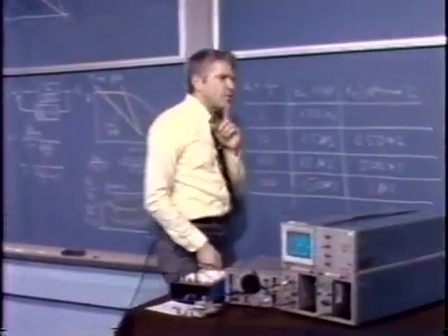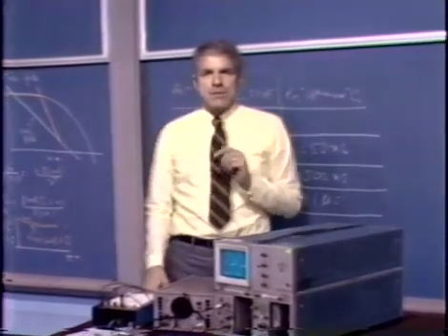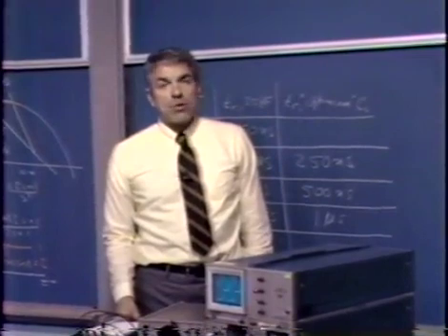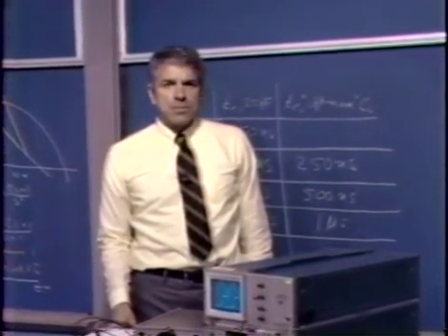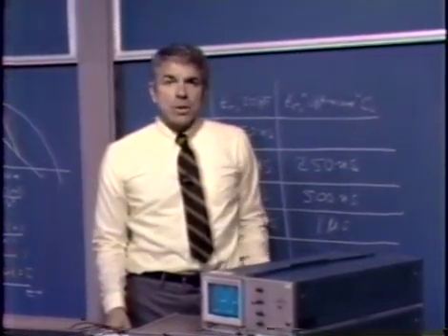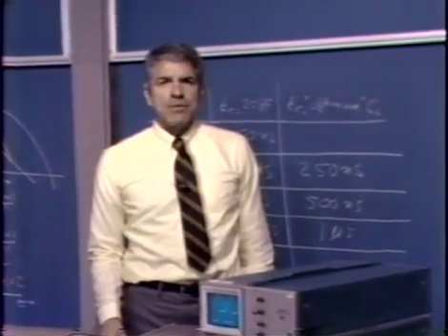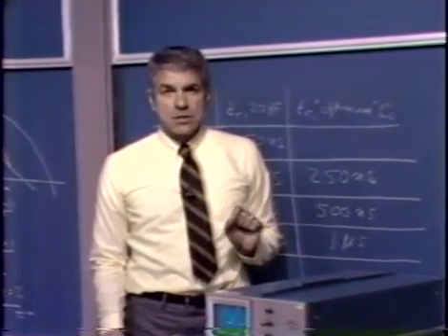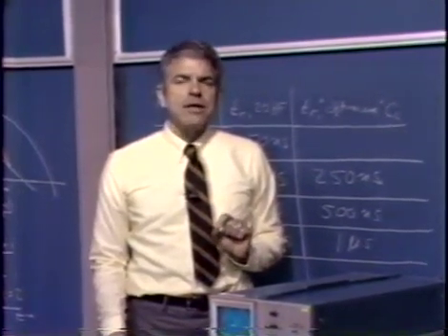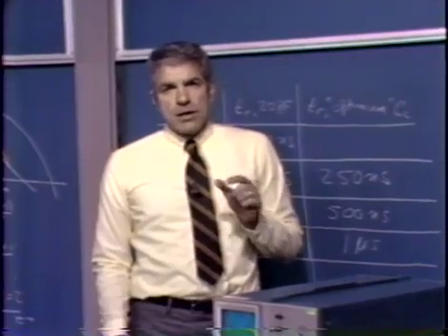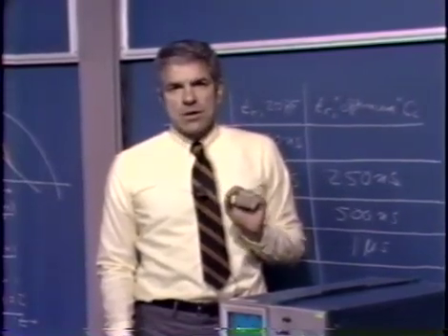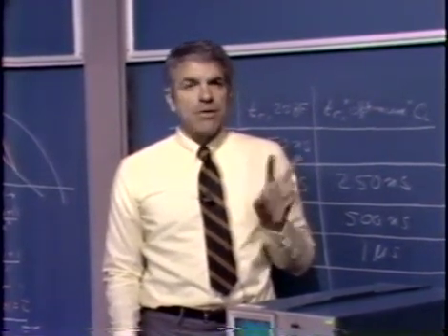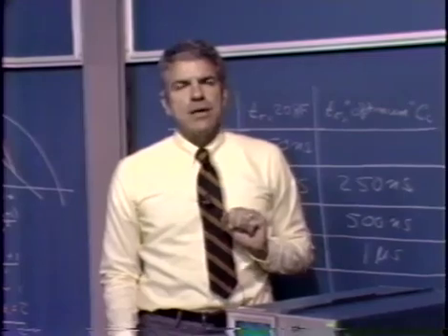Well, let's see. We said that when we use single pole compensation, the open loop transfer function of the operational amplifier over a wide range of frequencies is proportional to 1 over S. That's what we mean by having a single pole roll-off. The amplifier looks sort of like an integrator from its differential input terminals to its output. Alternatively, the output voltage of the amplifier is the integral of the voltage applied at the very input terminals of the amplifier, not the input of the overall feedback loop.